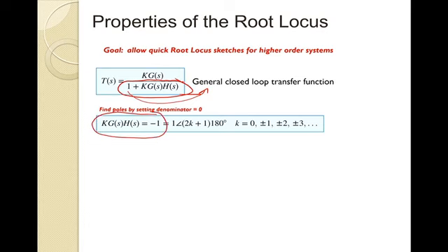We're going to say kgh equals -1. After setting that to 0, let's move the 1 to the other side, and that'll become a -1. And as we do that, when we say -1, what does that mean physically here? We could say that's a magnitude of 1, but the angle is 180 degrees.